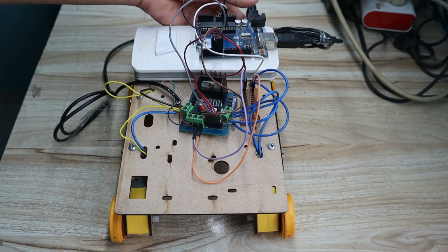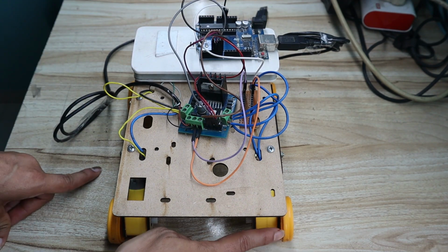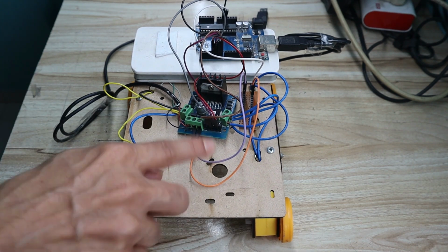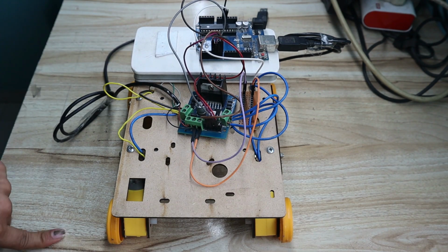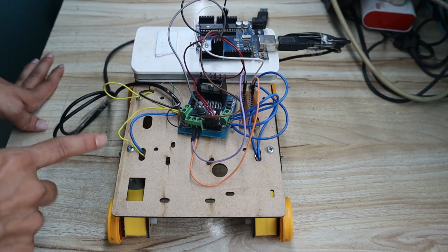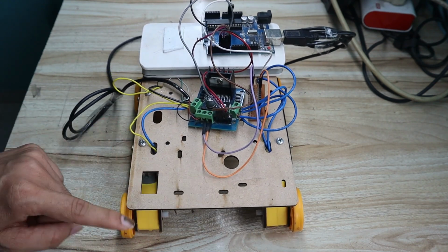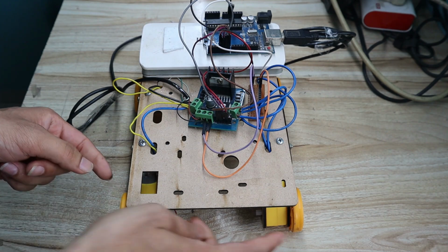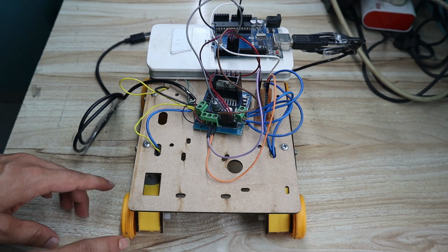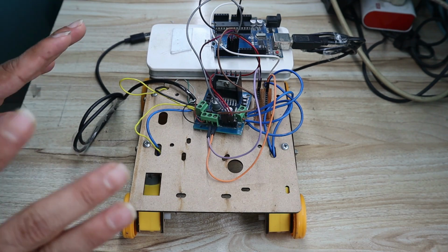With that, what we have to achieve is to check whether all the motors are rotating in the same direction or not. To move this bot in the forward direction, all these motors should rotate in forward direction. To move the bot in reverse direction, all 4 motors should rotate in reverse direction. To turn to the right side, this side motor should rotate anti-clockwise and this side motor clockwise. To turn to the left side, this side motor should rotate clockwise and this side anti-clockwise. So this is our initial target.